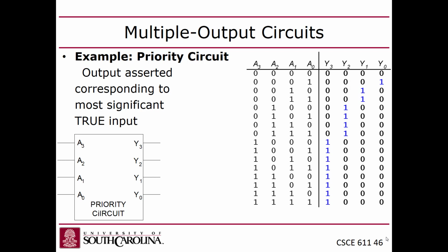Does that make sense? Right? So for example, in this first row, there are no 1 bits here. Second row, there's a 1 bit, and it's all the way to the right. So A0 is the furthest to the left 1 in the inputs, and thus we mark Y0 to 1, right?